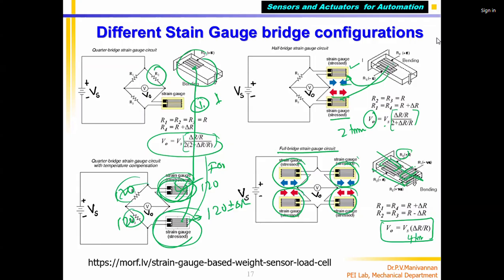But please note another thing. R1, R2, R3 have a resistance of 120 ohm. And they will not change resistance, even if temperature changes, even 20-degree change, 30-degree change. Very special resistors. They are called fixed resistors. They also should not vary. If they vary, there will be a thermal drift. But there are special ones available. The whole thing is available.